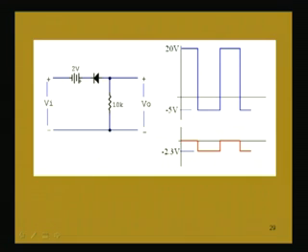So, we get 0 voltage in the positive half cycle, it will not be conducting, the resistance R or 10K will not have any current through it. So, this voltage is 0 in the positive half cycle, but in the negative half cycle the voltage will be clipped at minus 2.3 volts. So, this kind of an output voltage waveform we will be getting for this circuit.